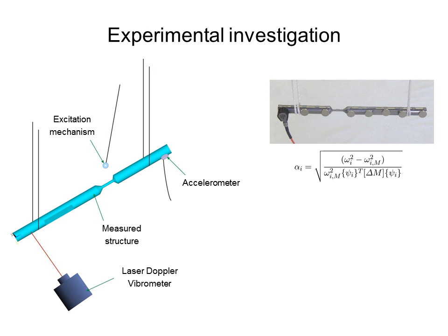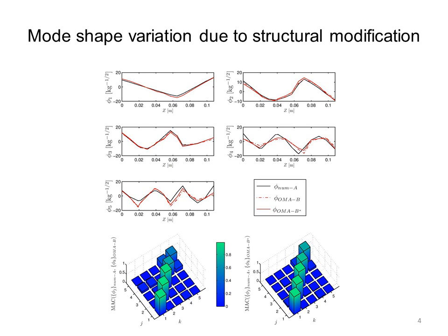Two simultaneous measurements of the response were needed for the operational modal analysis, and the excitation force was unknown. The reference response was measured by a lightweight accelerometer, and the second response measurement was performed by a laser Doppler vibrometer. The results of the proposed operational mode shape normalization method were compared to the results of the experimental modal analysis procedure and to the numerical model.